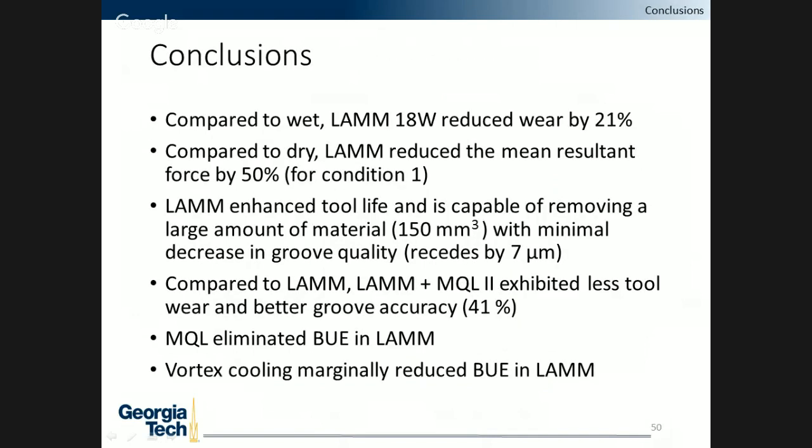And this is just the overall conclusions for experiment 1, 2, and 3. LAM was more beneficial than wet assist and greatly reduced tool wear. LAM reduced forces significantly. For cutting condition 1, it was seen to be 50%. LAM is capable of preserving the tool for machining for extended periods of time with only a marginal decrease in groove quality.